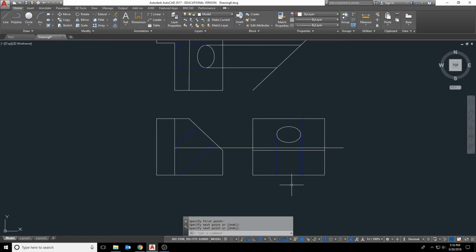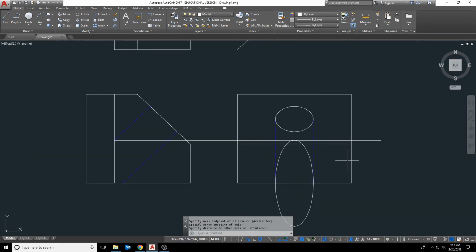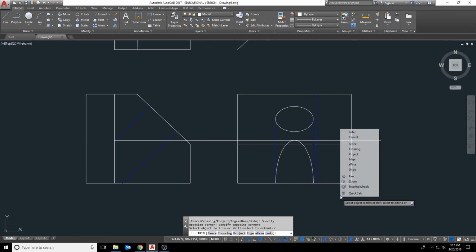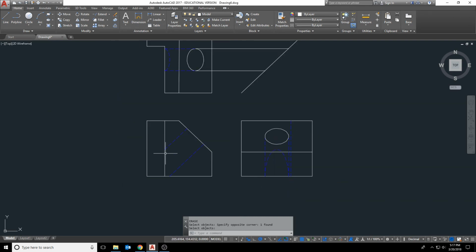This is going to be a really weirdly shaped cut coming out the back because it's such a large hole. So the ellipse that I have in this case is going to be from here to here all the way up to this. Then I can trim out the bottom side of this, make the rest of this hole hidden, and get rid of that line. So this shape right here is actually how that hole looks as it cuts through the back surface of this part, which we can see that that total height is here. This ellipse right here represents the part of the bottom that we can see.